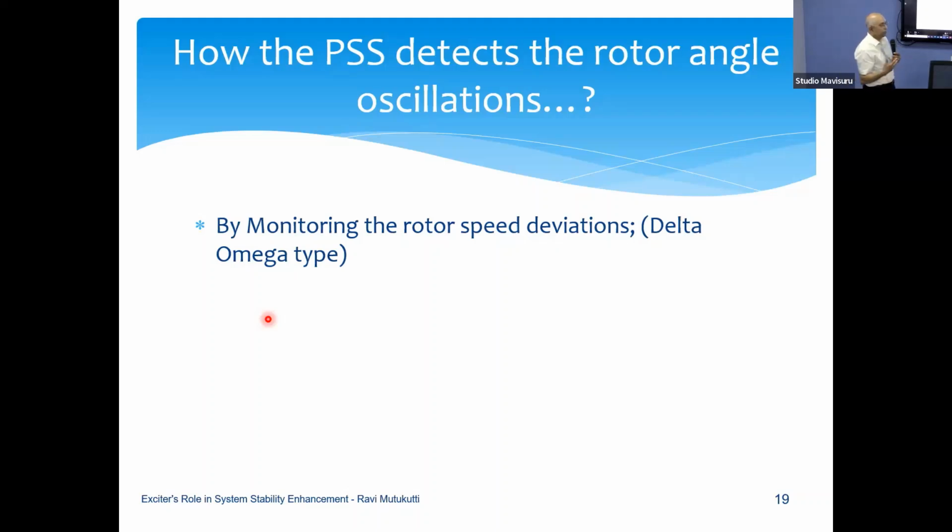So this rotor angle that I mentioned is not an angle that you can measure. It's not an angle where you can go on top of the rotor and measure the angle between two magnetic fields, because it is not an easy thing to be on the rotor. So you need rotor instrumentation if you need to determine this power angle.